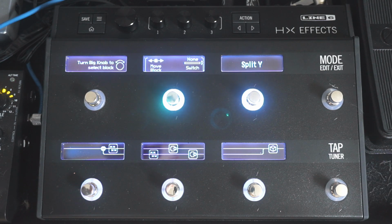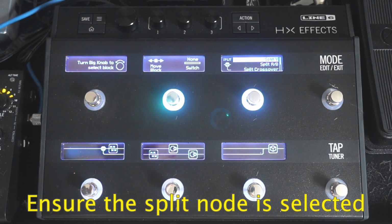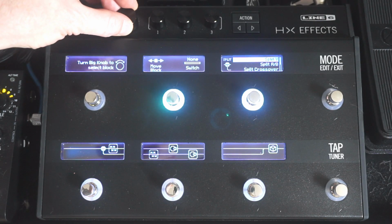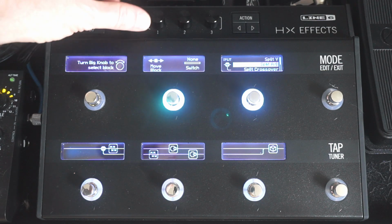But there are a number of different options you can choose for this path, and to do that you press the big knob button and you can see the different options we've got. So we've got split Y, split AB. Now that allows you to choose the amount of signal that goes to each path. So you could have 60% going to path A, 40 to B, etc.